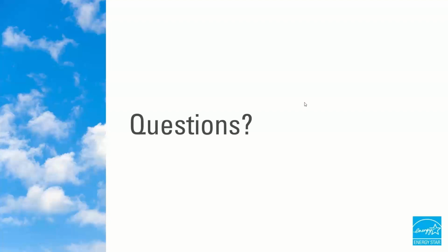Well, thanks, Dean. Regarding the reference design and smart or responsive thermostats, I think programmable ones might fall into that category. They're asking how this can be addressed for heat pumps that don't run or respond to third-party thermostats and just use built-in controls. So there's no mandatory requirement to use a programmable thermostat or a demand responsive thermostat either. For our Energy Star reference design, we've long had a programmable thermostat as part of the reference design. That really doesn't change for heat pumps.